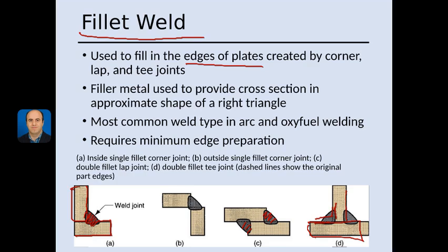For example here, as you see, this part is not welded, so it is not full penetration. In that case, you need to do some joint preparation. The fillet weld can be used in arc welding processes as well as the oxy-fuel welding process.